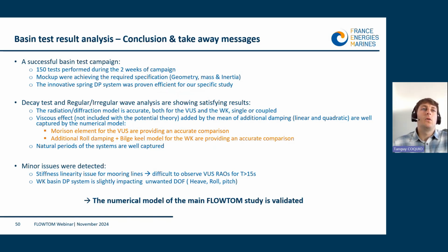The more recent elements on the floater and the additional roll damping to represent the bilge keel drag effect on the vessel are providing an accurate comparison. Natural periods of the system are also well captured during these comparisons.